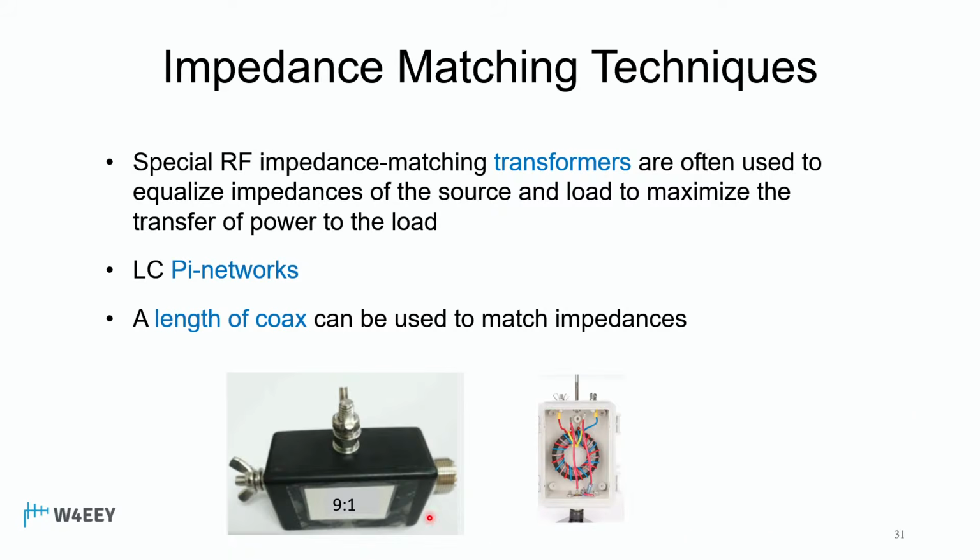So what are some techniques? Down at the bottom of the page here, I've got a couple of boxes. Let's say that you want to be using an end-fed antenna. Let's say an 80-meter end-fed antenna. That's going to have very high impedance at one end of that wire. So we have to use a matching box, typically 9:1. There's other ratios that are used. A lot of times this is what it looks like. The coax from your transmitter would go in over here. The wire would get attached here. And then some people will put a counterpoise on this one or ground it. But most people just leave the other one disconnected.